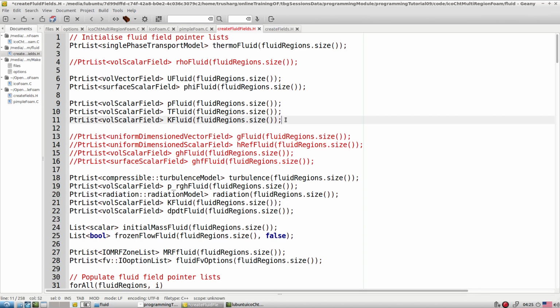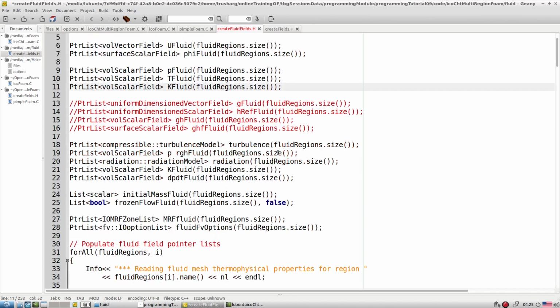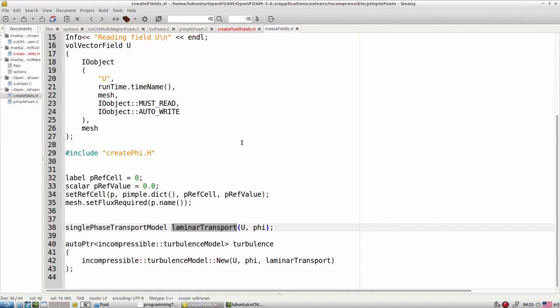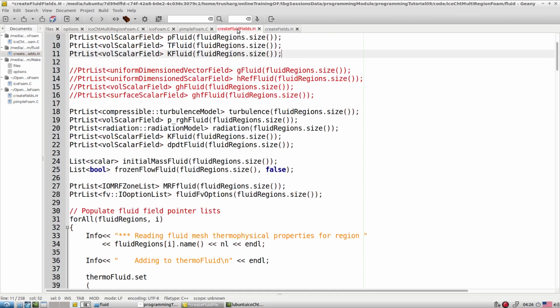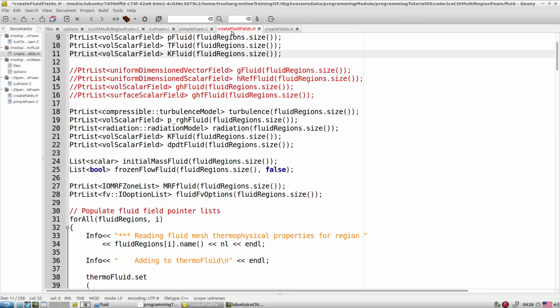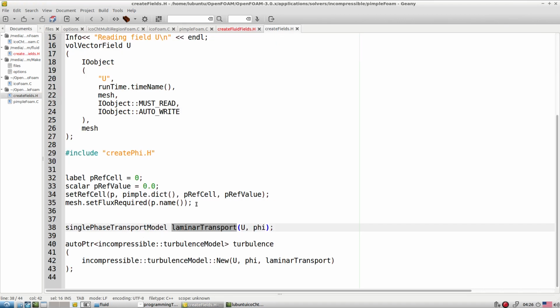Then also a few more things we require, that is some constants. So why are those constants needed? If you look here, in the incompressible domain we normally read nu, Pr, Prt. If we talk about the temperature, we require nu, Pr and Prt as some dimensionless scalars, and we have to read those.